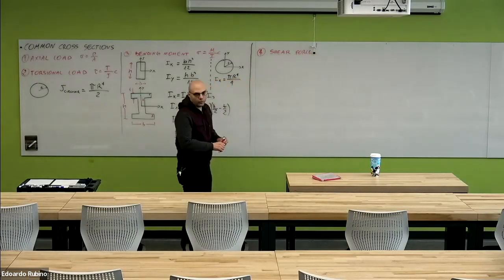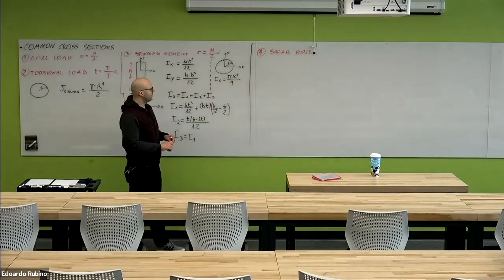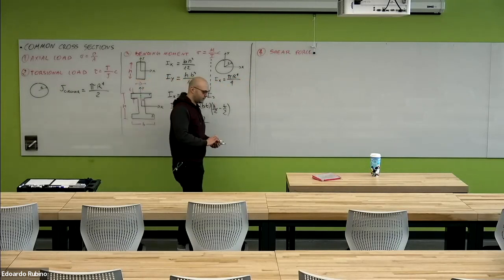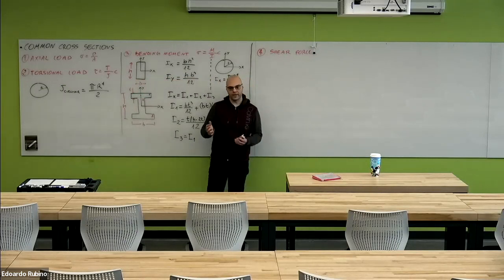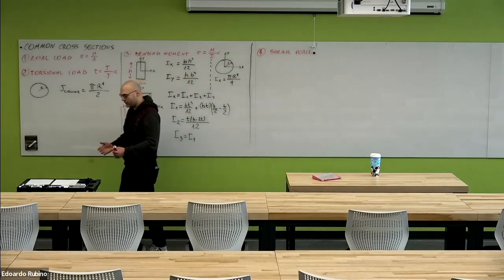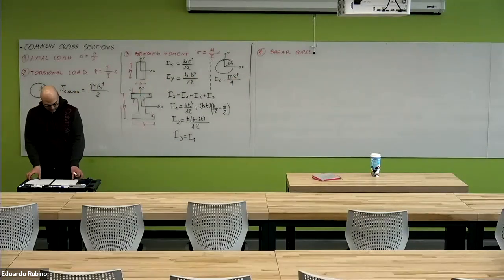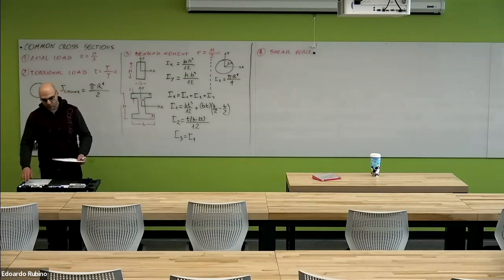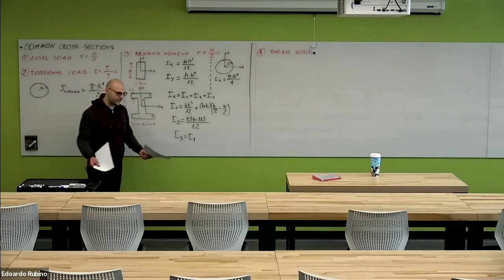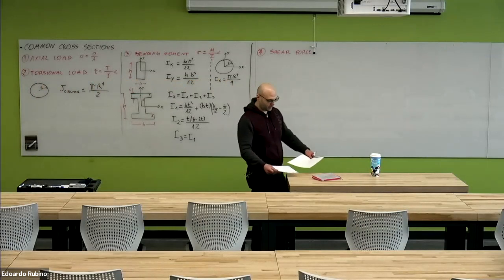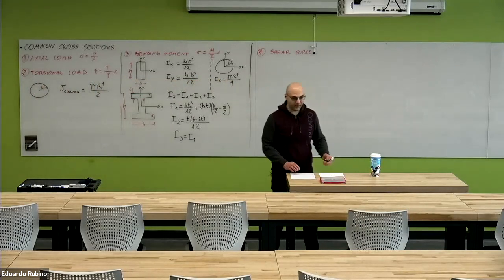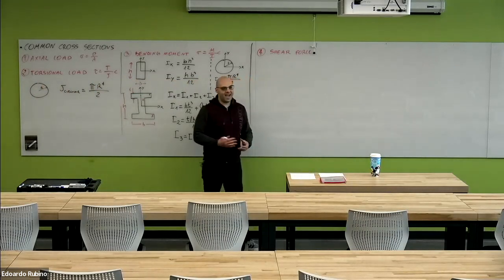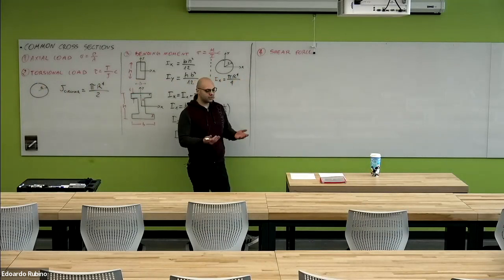All right, as we said before, in order to determine the shear stress, we can use the shear formula, which is VQ over IT. So now, actually, we can use even more simplified versions of this equation. We can estimate the shear stress on a certain beam by using the equation that gives us the average shear stress.